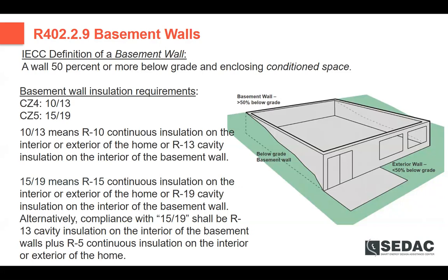Also noting here the slash, as far as continuous insulation, or you can add more if you're doing cavity insulation. Again, we don't see this too often in residential, but we'll be concerned if using metal studs, because metal studs eliminate about 2/3 of insulation's performance. So an R30 insulation product in the cavity of a metal stud will only perform about like an R10.